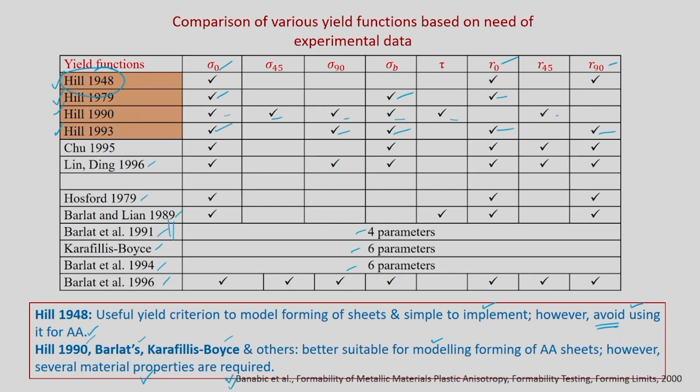So, this is what we can discuss about anisotropic yield function. We have seen 4 important yield functions, predominantly Hill 1948, and Hill 1948 also we rewrote that equation in a few different forms. That is the main thing. Next important one is using the Hill 1948 yield function, we derived the relationship between alpha and beta, which was earlier for us a simple one without considering R value. This alpha beta had R value in that equation, which can be used for anisotropic sheets. That is the main thing.